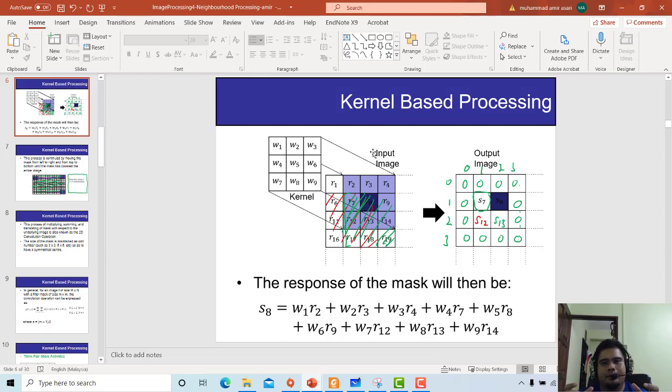But if you remember, in the convolution process, the flipping mechanism is essential, because if you don't flip one of either xn or hn, then that is not convolution. You must flip one of them, then after that you can slide across the entire image. But in two-dimensional convolution, it seems we skip the flipping process. We just directly take the window, or the filter, and do a sliding process over the entire image.